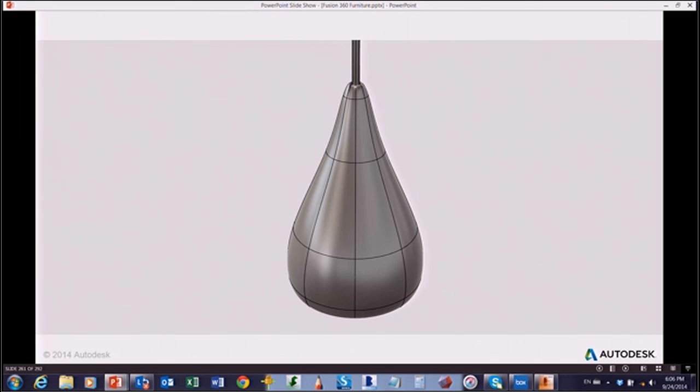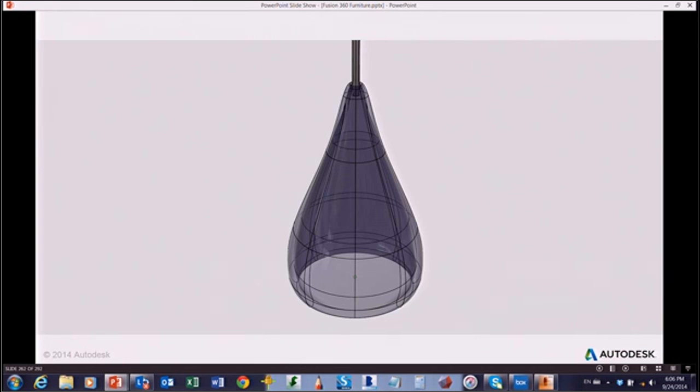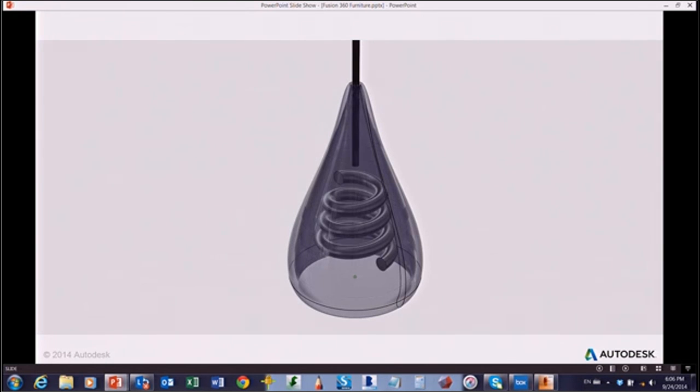And perfect transparency, I had to do this twice. My first model wasn't perfect. I brought it into Revit, and the whole thing unwrapped, so I had to try it a second time. That's the one downside. It's not a regular workflow. Your model in Fusion has to be well done, and some of the little things might explode when they go to Revit. It has to be totally closed, totally good.